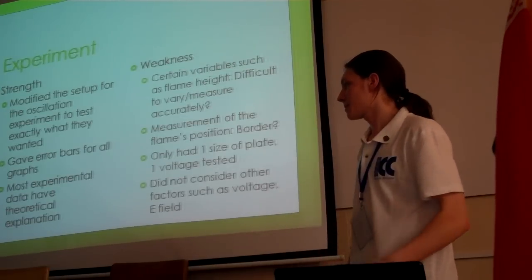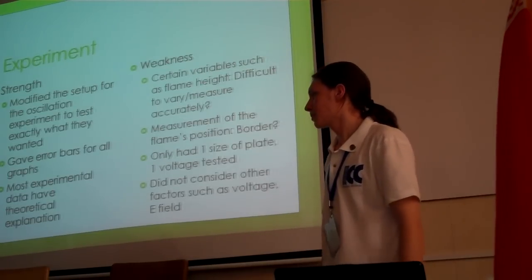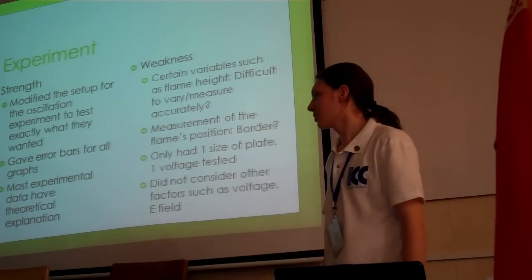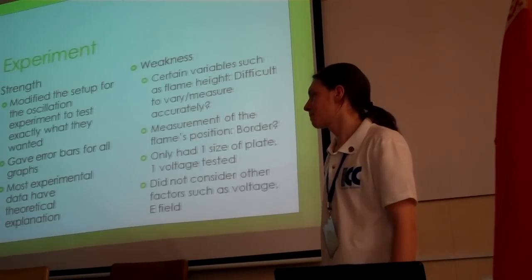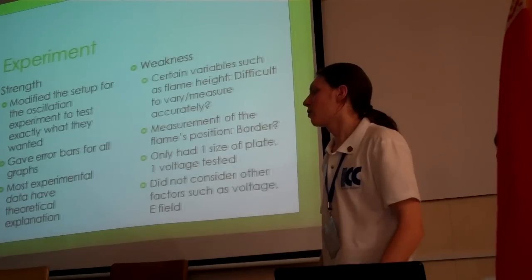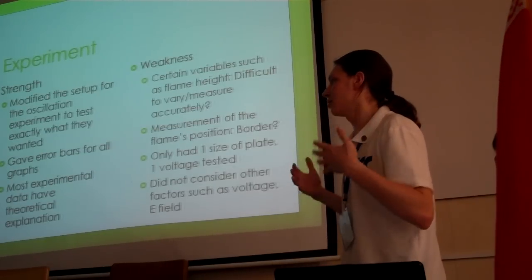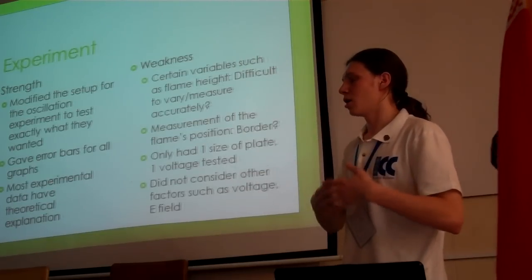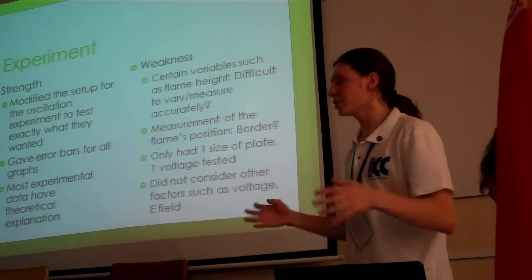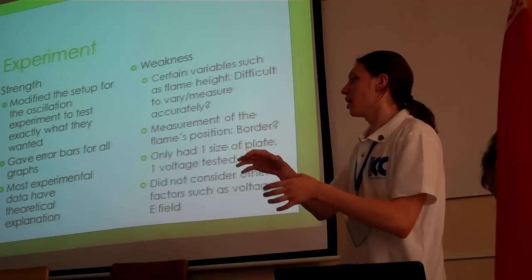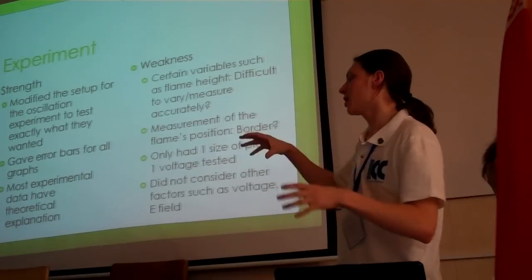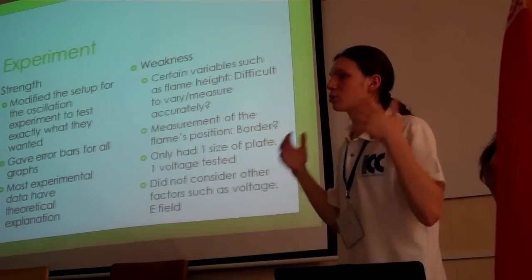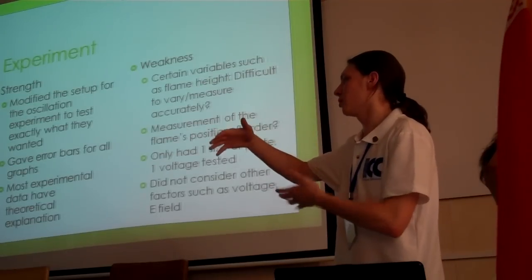Okay, thank you. When you were doing the demonstration, I noticed that the popping sound occurred at this separation when the flame is there. However, when the flame is removed, you had to move the plates much closer before arcing occurs. Yes, of course. It's easy to understand because our flame produces ions, and due to chaotic movements of particles some ions leave the flame. And when we have the whole flame which has some charge and some ions outside, a breakdown can easily be caused between two charged substances.